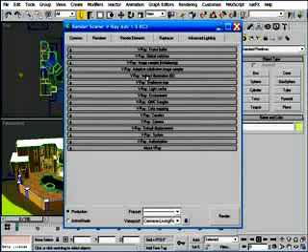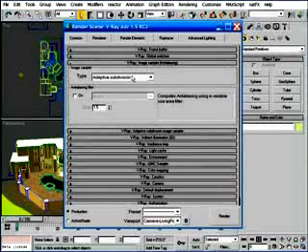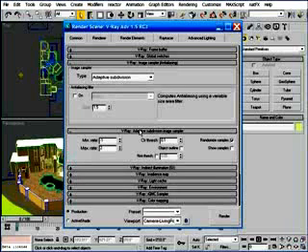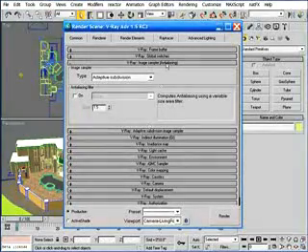Next, I want to go to the image sampler, and because of all the large, smoothly shaded surfaces, this scene is a perfect candidate for the very fast adaptive subdivision sampler. Although this may certainly change once I add furniture and other details, for now I'll leave this sampler enabled. I just wanted to point it out because image sampling is so important. I want to use this sampler, and the default values are really ideal for quick test renders. So I'll leave everything here set as is.